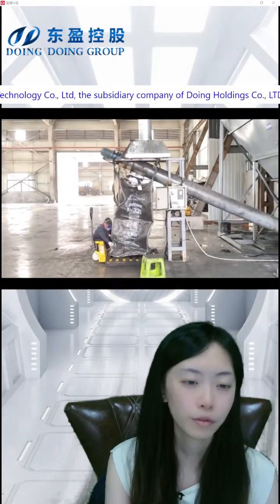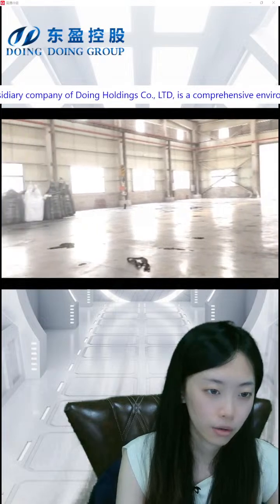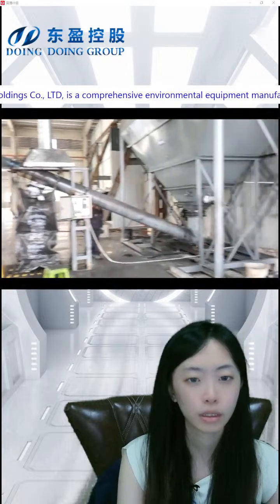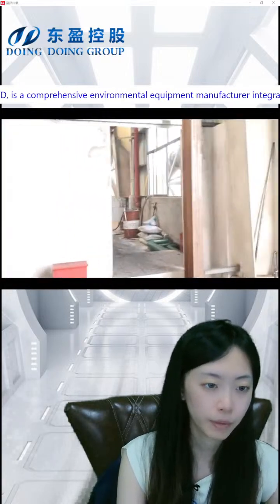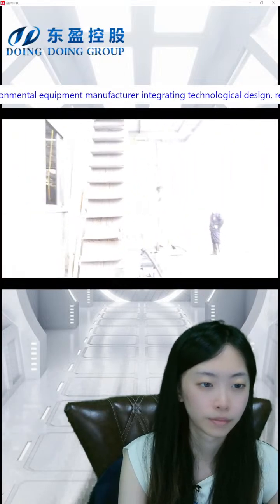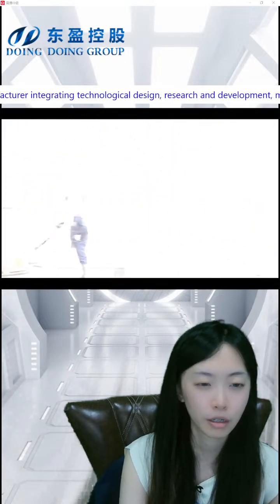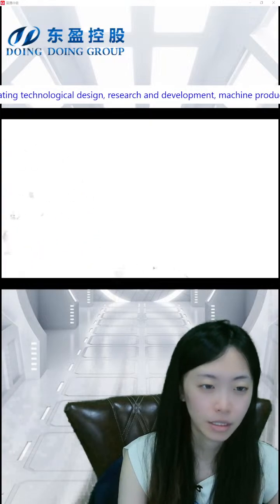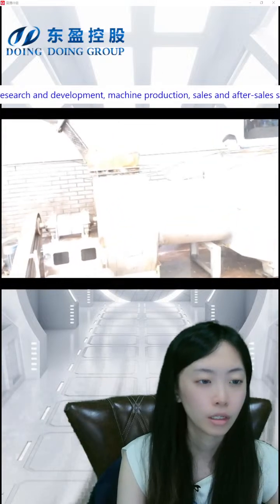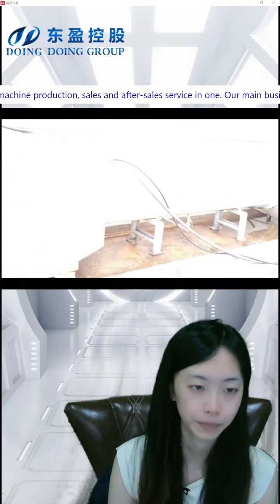So, if you have the solid or semi-solid coal tar oil or oil sludge, it has low oil or water content, but a high amount of residue. It has many kinds of soil, because it has accumulated for a long time, so it will have some soil mixed in it. So we have to use the batch type furnace, the batch type pyrolysis plant.